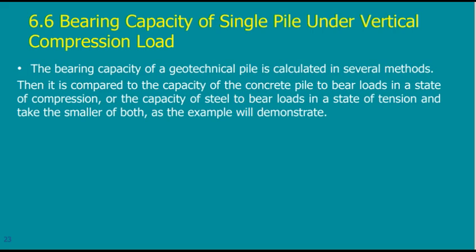In case the pile, imagine that you have a pile made of concrete, pile made of steel, pile made of glass. Of course, each pile will carry a different load, regardless of what the soil can carry. The soil can carry a certain amount of load, but the concrete section itself may be less. So I have to calculate both and to choose the smaller.